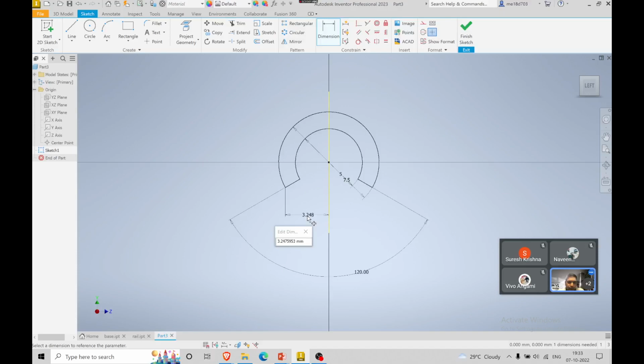So now slider part 4. So first what we will do, we will create this square. So this rectangle. This is dimension 15, and if I slightly move this, you can see here it is 10 mm. So 15 by 10 I am going to create a rectangle. I am going to extrude it for 20. So let us do that. So again, which view we have to check, because while assembling it will be easier, convenient for us, otherwise we need to rotate it and those things. So this also in the left side view.